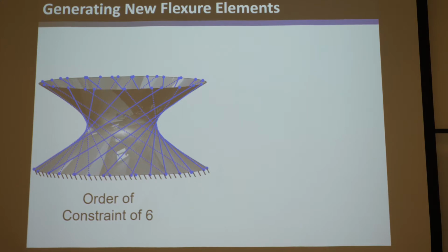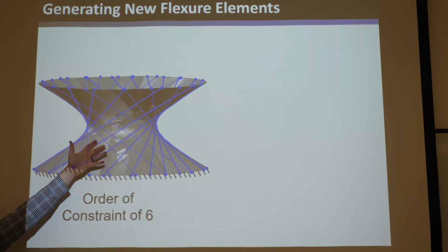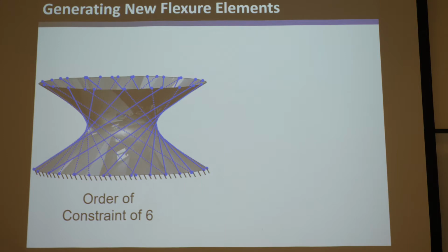They just have orders of constraint. This is an order of constraint of 6, and therefore it would be totally exactly constrained and would act like a structure. There would be no degrees of freedom. And this is, of course, why people make roofs and water towers and stuff out of this shape, because as long as you have both sets of rulings, either in the shell form or as trusses, straight beams, it's actually a very stiff shape that constrains all directions.